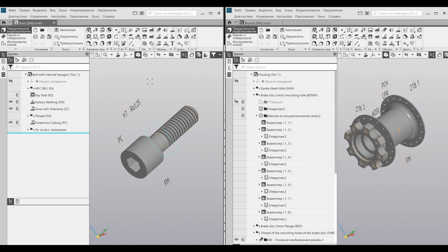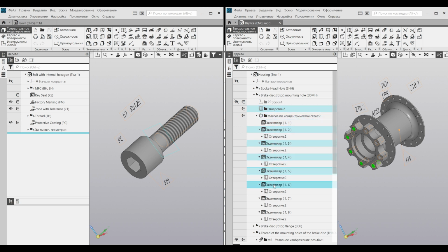If the structural model contains the same function carriers, for example, the same holes, the same flanges, the same threaded surfaces, they are indicated in the construction tree by the same name with different indexes. For example, if you gave the carrier of the function hole the reference abbreviation HL, and we have 3 identical holes in the part which have the reference abbreviations HL1, HL2, and HL3 in the table structural model, then they will have the same designation in the construction tree.